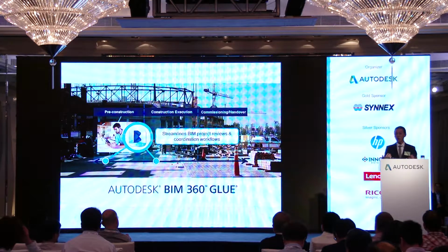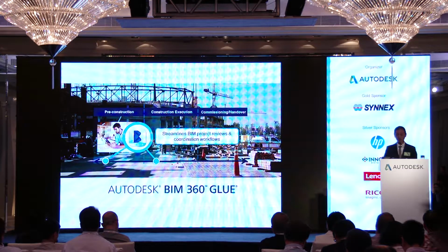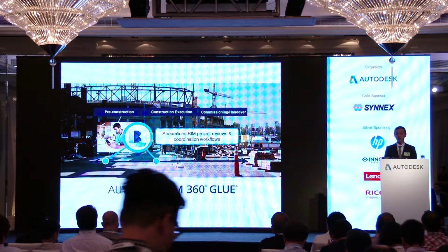That has worked quite well, especially for FM, on all the electrical panels that he needs to maintain in the future. So he needs to have a specific equipment ID. We generate all the equipment IDs from Revit. We load up the project browser, put all the equipment IDs into Revit parameters, and you can see the exact data from Glue as well.